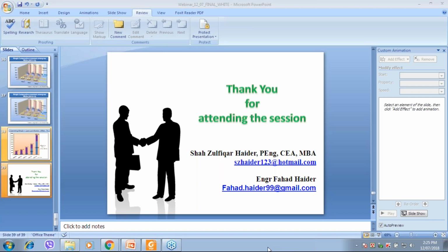Yes, that was a challenge, but in Bangladesh, we had a master plan and we had the block load study at the field level. There are two things we experienced: the massive growth of industries, and then new systems of their own. Another thing is that with the improvement of the economy, the customer pattern has increased. So whenever we construct any substation, we have a provision for future expansion, so at least 2 to 3 new feeders could be brought out.